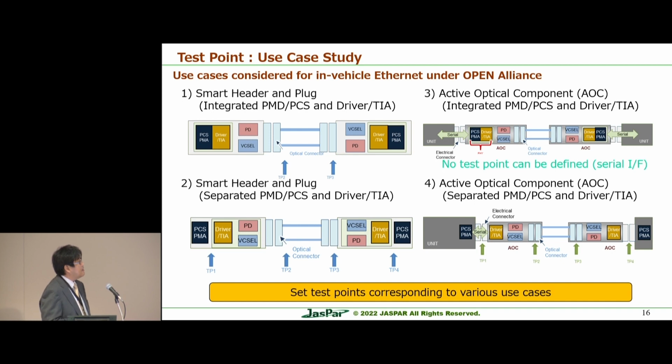So finally, the active optical component separates the PMD and PCS, and the PMD driver, the so-named PHY chip, is integrated in the ECU unit, with the electrical signal using the electrical connector, and the fiber optics component element is integrated in this one.